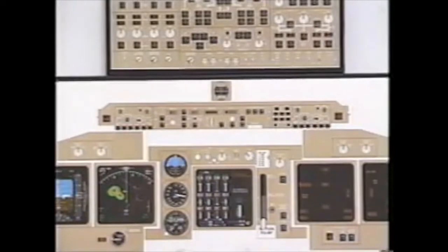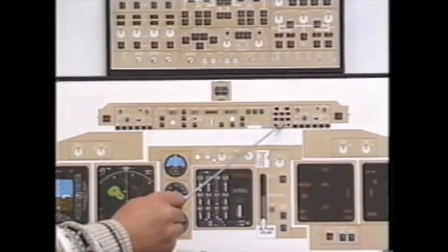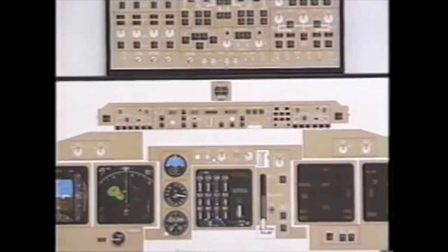Our review now will move to the glare shield, which encompasses the EFIS control panels for both the captain and first officer, ICAS control panel, and mode control panel. EFIS control panels allow the pilot to select what's displayed for the PFD and ND and change various modes. If the EFIS control panel was to fail, moving to the CDU, the CDU menu page allows us at line select one right to select EFIS control panel to control those functions in the event that the real control panel was to fail.